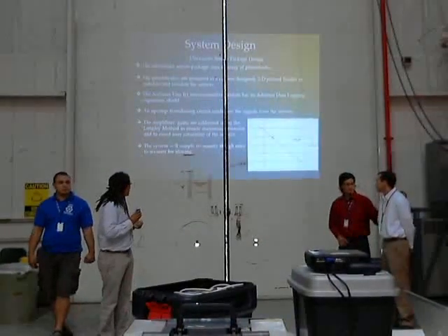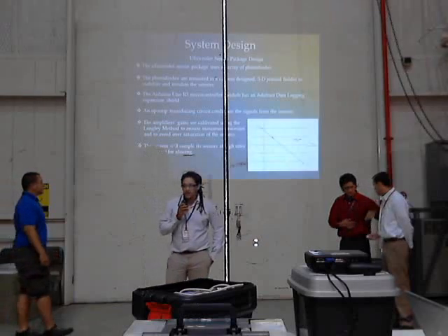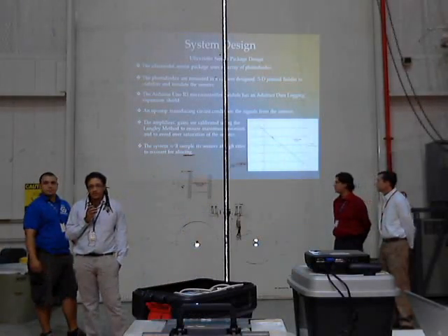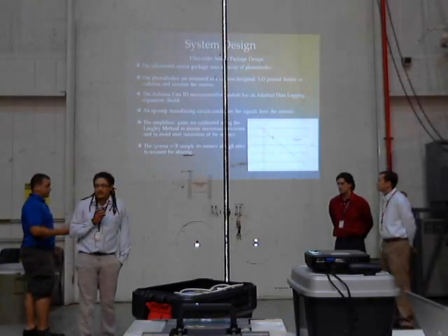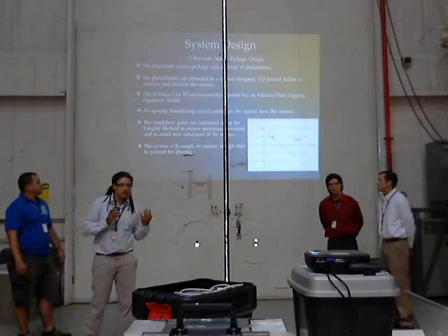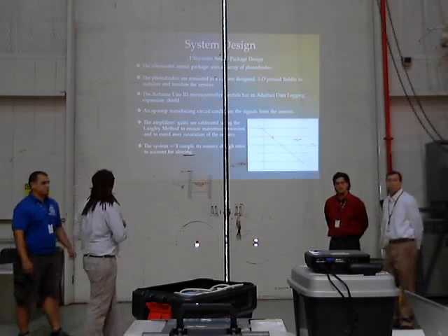The gains were calibrated using the Langley method to estimate the maximum voltage we would reach above the ozone layer, and to avoid saturating our sensors. We also sampled at high rates to account for data aliasing.